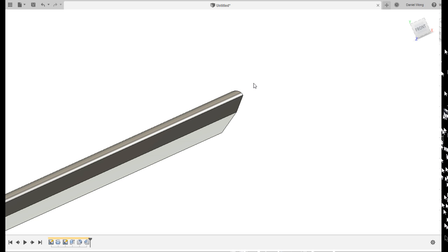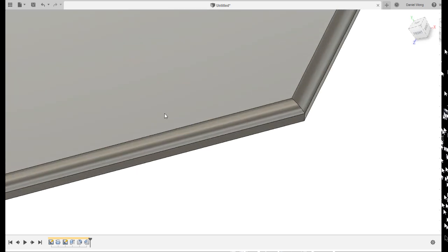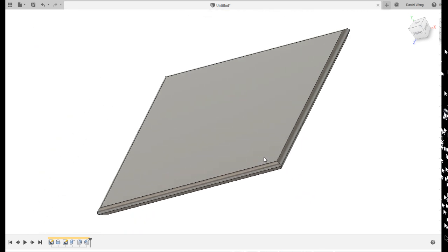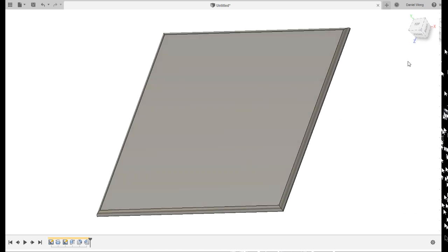Right. So now we need to build a recess for all the sandstone tiles. Because we obviously need those. It's not sandstone, it's limestone, I think it is. We're going to need a spot for the tiles, because obviously they're going to fall off the table if they're just put on this table right here. We're going to need some sort of recess. So I'm going to make a recess that is 77.5mm from each edge here.